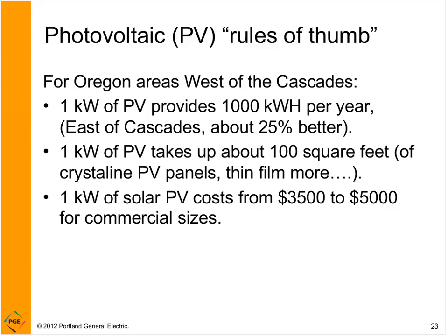We may not know what will happen tomorrow. We may not know how good a month this month will be, but on average we can say over the course of a year that sunshine will generate so much power if you have a 1 kilowatt system on your roof. So I've used a 1 kilowatt system as a building block here, to make it easy to multiply out. If you have a 3 kilowatt system, just multiply all these numbers by 3. But basically a 1 kilowatt system, now that means that the panels are rated at 1,000 watts.